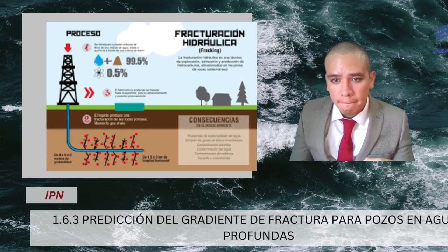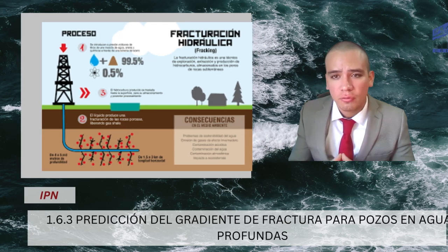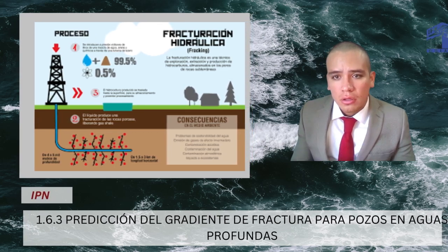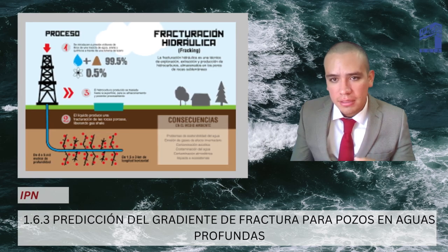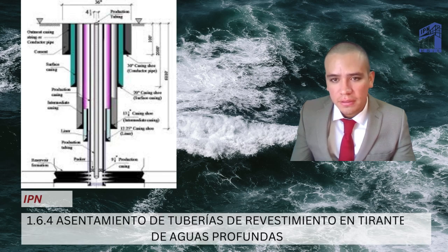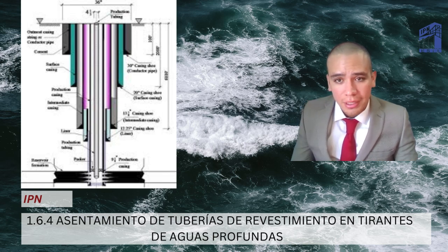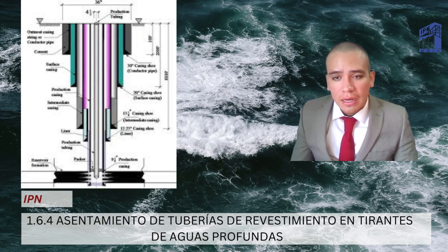Catenary curves. The suspended portion of the mooring line falls under its own weight, forming a curve known as a catenary curve. The ratio of the total length of the mooring line to the water depth is called the reach. Mooring lines for floating drilling units generally have a reach of 5.0 to 7.0, a total length that is 5 to 7 times the water depth.